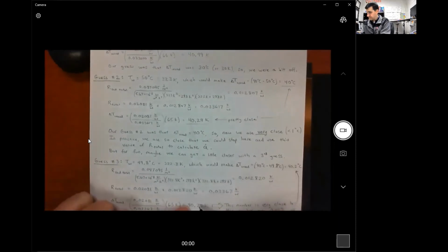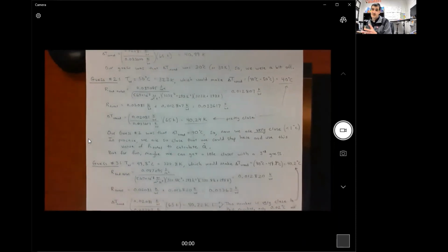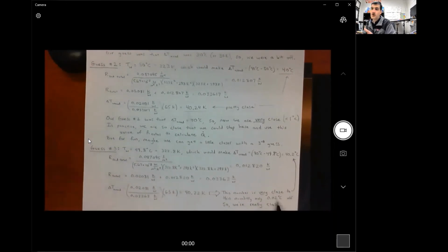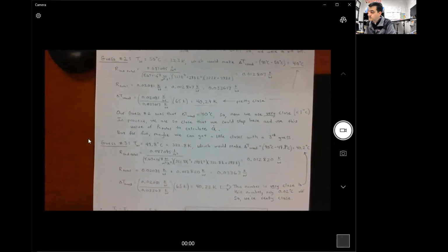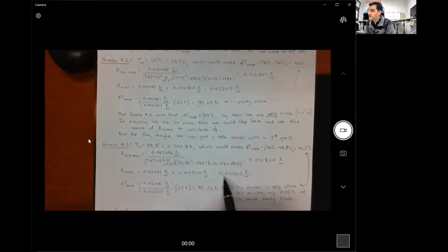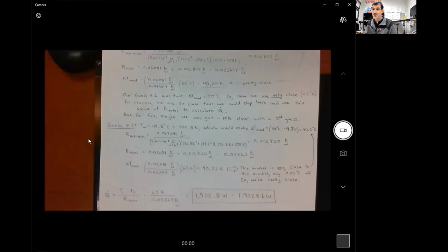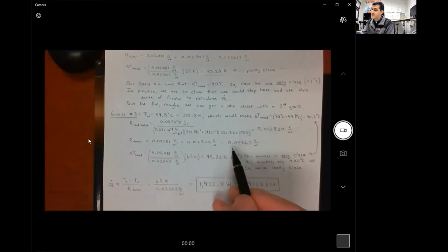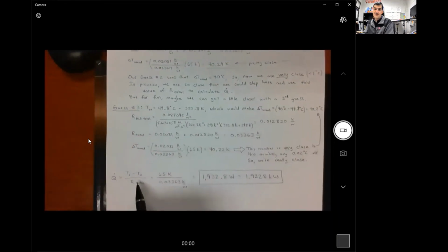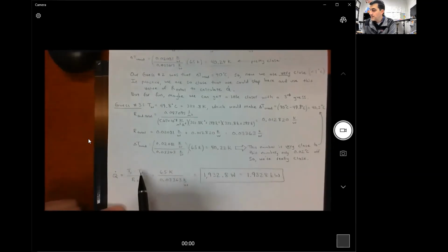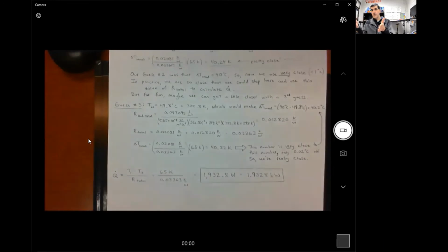So these are really, really close. That's a really good assumption, a really good estimate. It's only 0.02 degrees Celsius, or 0.02 Kelvin, different. So we can now use this number for our total in our calculation. The rest is really easy. We just plug that value of our total into our basic heat transfer equation. T1 minus T2, that's the temperature inside the barrel to the temperature of the walls.